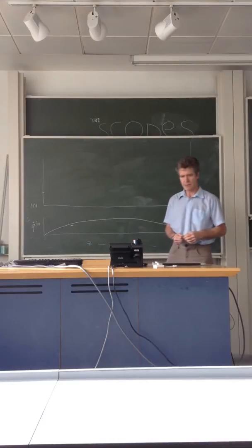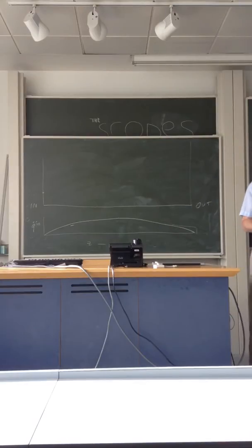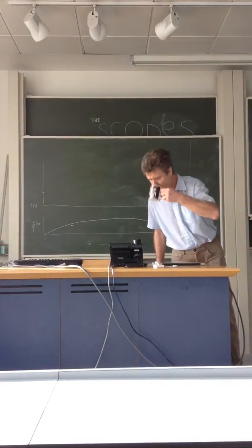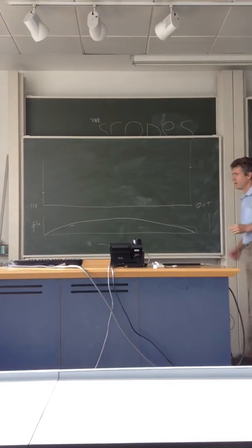So this is, say, the inlet coolant temperature. So it starts. Temperature graph. Yep, there's going to be temperatures up above there. So it comes in at one temperature, goes out at another. And roughly how different are those, say for a PWR, those two numbers, inlet and outlet temperature? Just always helps to have a physical idea. Sorry? 30-ish, yeah. Remarkable. Whereas it's an order of magnitude more than that for an AGR. So just quite different behaviours.